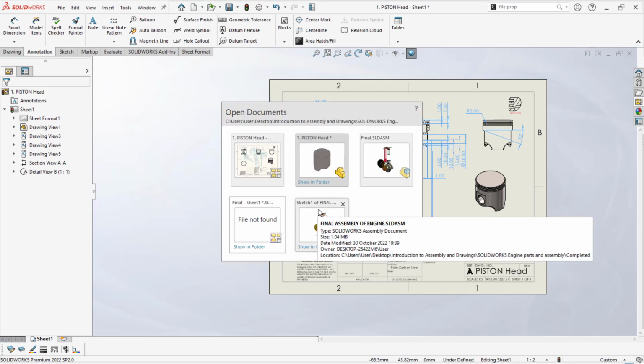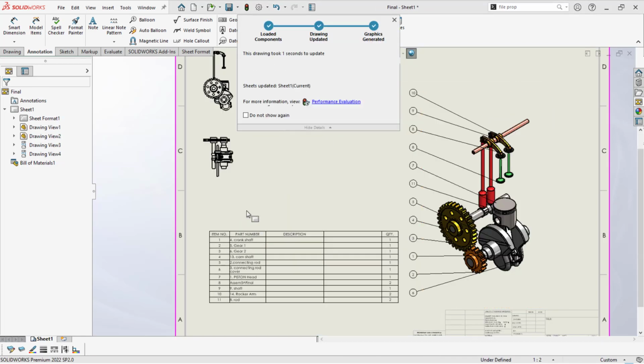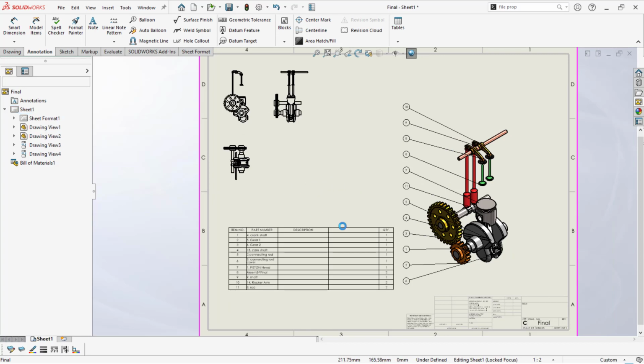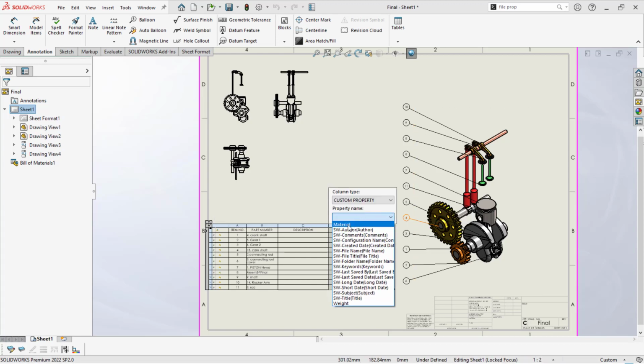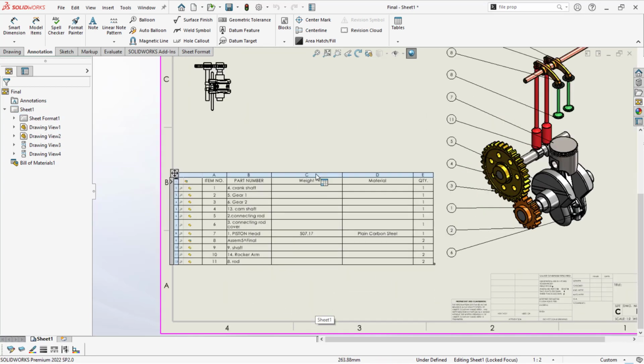Once this is done, let me go back to the assembly drafting and showcase how to update the material here. We had customized our template in the part, so it should appear here, right? You can simply delete or add the properties here. Can you see the material and the weight got additionally added? If you want to change the previously added custom things, you can just use the drop down and add weight and material, like this.